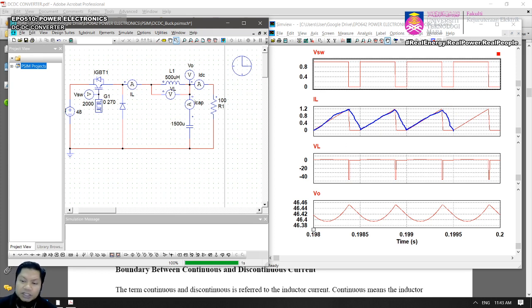It is important to determine this because you can actually design the circuit so that it won't fall into discontinuous operation. So you protect your circuit so that it doesn't work under discontinuous operation. So we're going to determine the components, just now I changed this, isn't it?